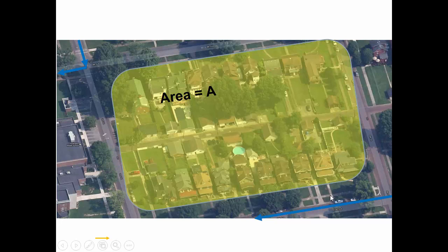Like maybe down in the lower corner there's an inlet grate that receives all of the flow from this area. And a raindrop on this side wouldn't get to that grate. It's going somewhere else. And the rainfall here also isn't going down into this grate. But the boundaries of this contributing area just means that all of the rain that falls within these boundaries has the potential to aggregate at a single location.